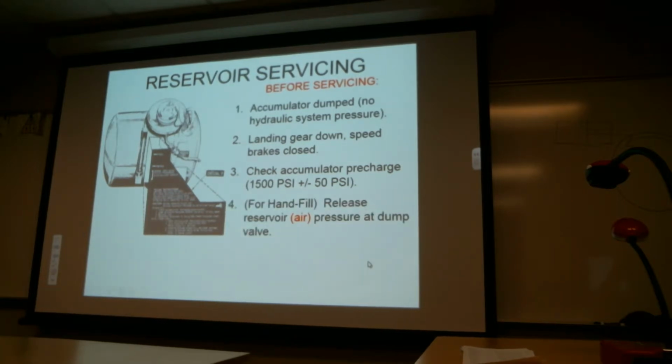And it says for hand fill, release the reservoir air pressure at the dump valve. So what you do, before you open the filler cap, since it's an air pressurized reservoir, is dump the air pressure so we don't get sprayed in the face with fluid. And then lastly, it says before engine start, pressurize with air to 70 psi plus or minus 20.